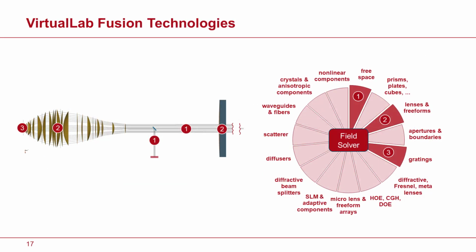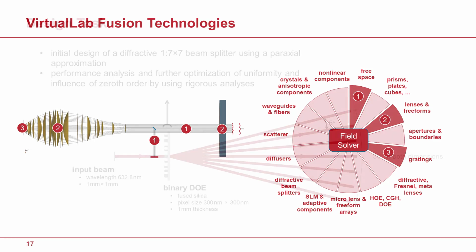We're going to select one solver for the free space propagation steps, a different solver for the smooth surfaces that define the lenses, and yet another solver for that wafer, for that grating, that periodic structure. And then the engine is going to put the solution of these algorithms together in a seamless, fully non-sequential manner, and that is going to solve Maxwell's equations for the whole system.